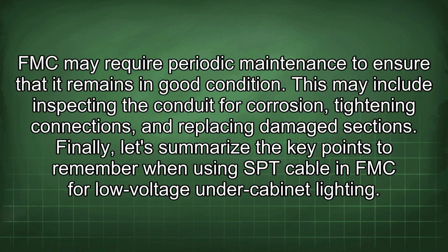FMC may require periodic maintenance to ensure that it remains in good condition. This may include inspecting the conduit for corrosion, tightening connections, and replacing damaged sections. Finally, let's summarize the key points to remember when using SPT cable in FMC for low-voltage under-cabinet lighting.